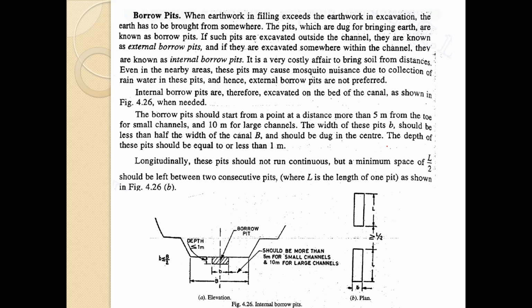The borrow pits. When the earthwork in filling exceeds the earthwork in excavation, the earth has to be brought from somewhere. The pits which are dug for bringing the earth are known as borrow pits. If such pits are excavated outside the channel, they are known as external borrow pits. If they are excavated within the channel, they are called internal borrow pits. It is a very costly affair to bring the soil from a distance, even if it is in a nearby area. These pits may cause mosquito nuisance due to collection of rainwater in these pits, and hence the external borrow pits